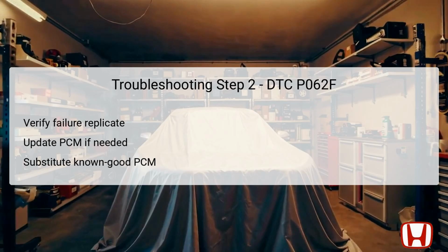This substitution will help determine whether the original PCM is indeed faulty or if the issue lies elsewhere. Care should be taken to ensure that all substituted components are compatible with the vehicle. Verification is crucial for ensuring that the root cause is accurately addressed.